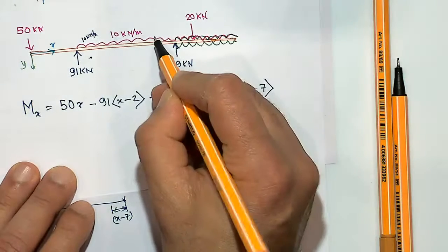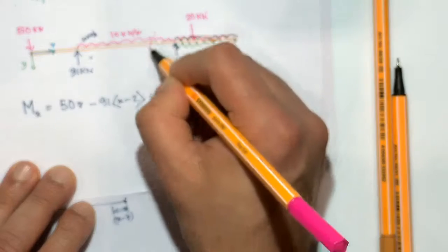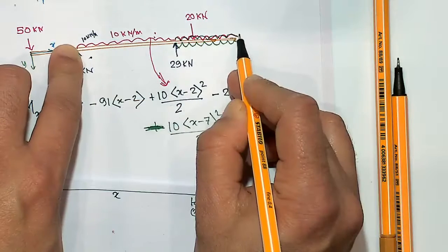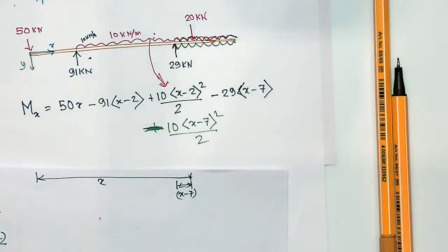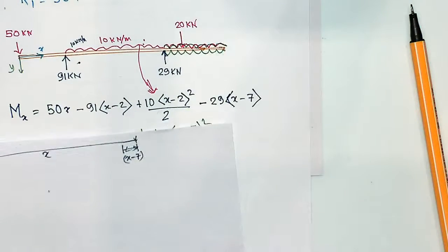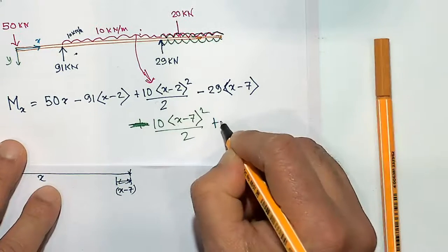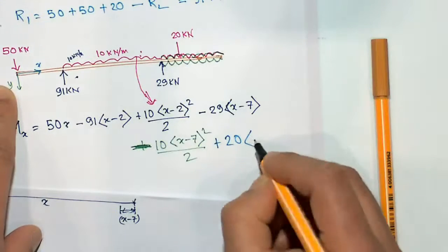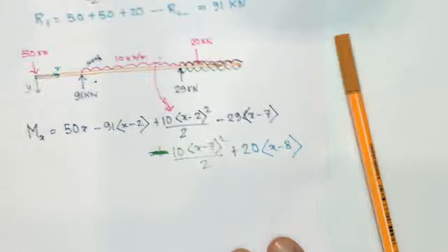So this expression, the pink load is given by this expression. So that means the UDL extends from 2 meter till the end. And then the green bit is acting upward, meaning these two cancel. And finally this 20 is creating an anti-clockwise moment. So that final bit of the 20 would be plus 20 times the distance, which is 2.578, so (x minus 8 meter). So if you get those expressions over here,